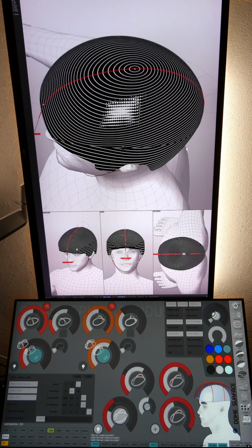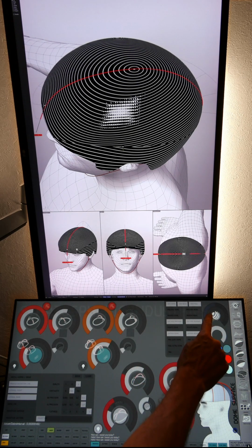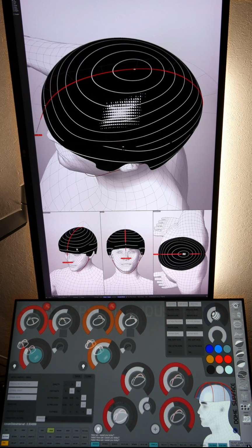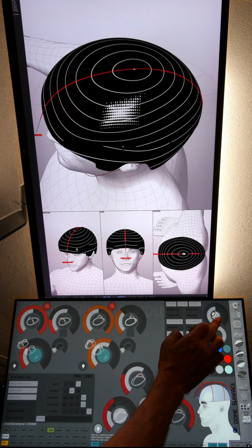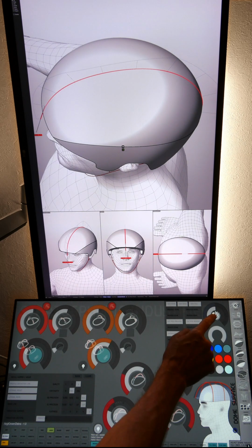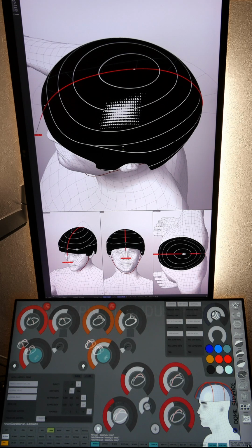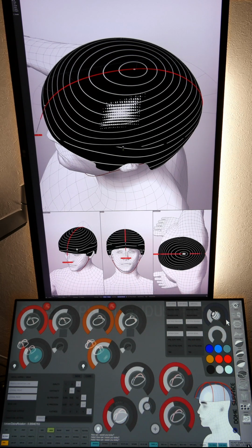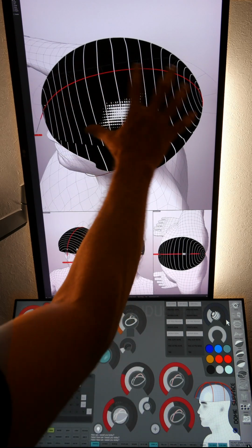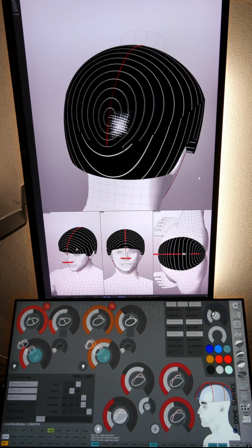I'll do some adjustments now with this in place. Again, as with most things here, the scale of the curvature can be changed. The angle with one dial, so on and off is toggled in the middle. Scale of the curvature display is controlled here. Bump that to something in the middle. And the angle at which that's being viewed is controlled with the outer dial. So that rotates this whole shape down to the back. Just looking at it there.